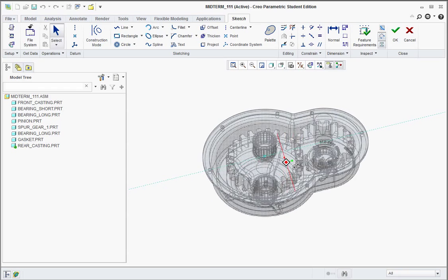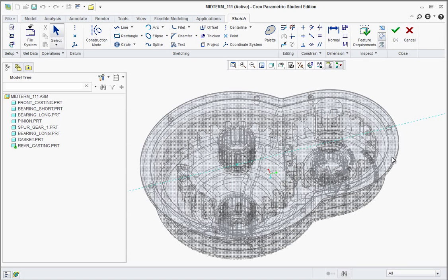Now what's nice here, if you're doing the top-down method, you're just stealing the geometry off the other parts, and they're permanently linked. If one changes, they all update, which could be, in most cases, a good thing if that's your intent. It could be a bad thing if you use it somewhere else and try and change those parts.